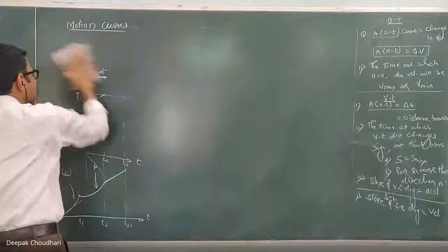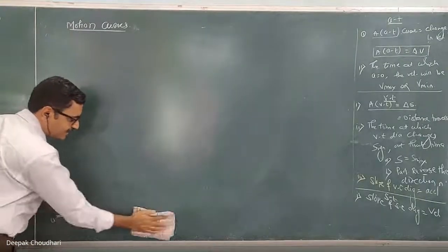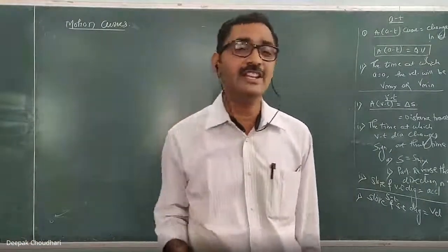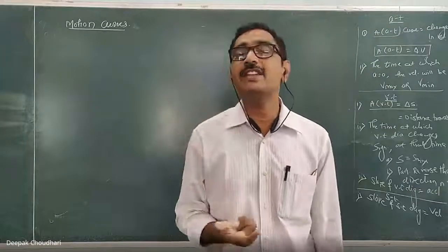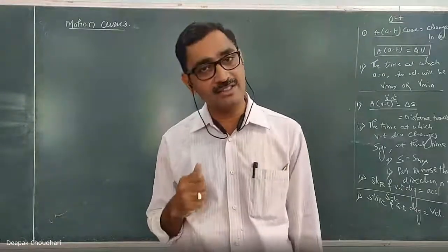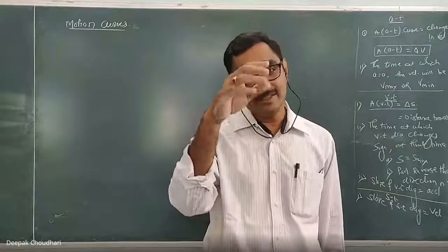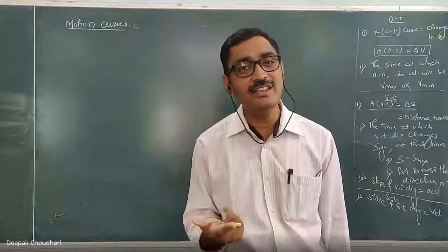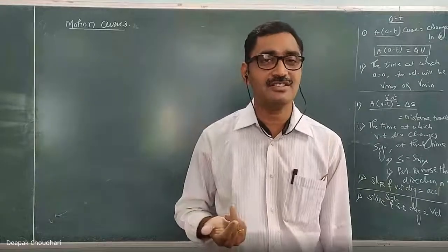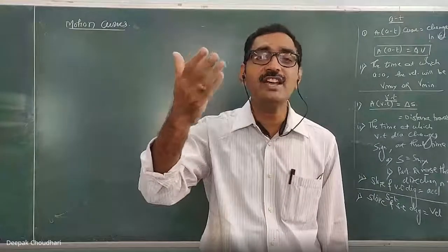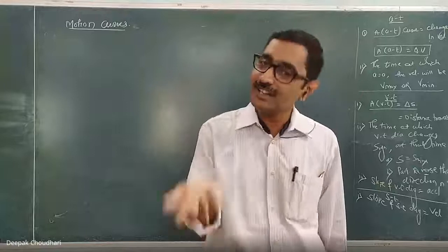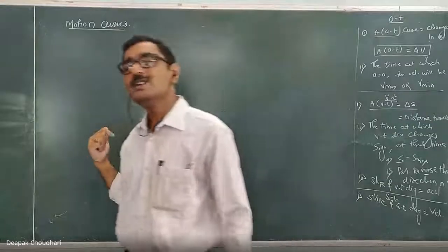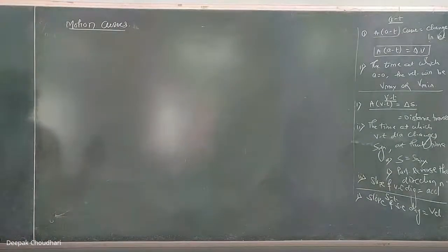Okay, now we'll solve one question. First, the nature of the AT, VT and ST diagrams. I told you that we get the velocity equation by integrating the equation of acceleration, and when we integrate any equation, the degree of the equation increases by 1. From this we can conclude that the nature of the VT diagram is one degree more than the AT diagram. Means if the AT diagram has a linear equation, the VT diagram will be a quadratic equation. If the AT diagram is an inclined straight line, the corresponding VT diagram will be a parabola. And the corresponding ST diagram is again one degree more, a curve of degree 3, that is, a cubic curve. You have to remember that while drawing the AT, VT and ST diagrams.